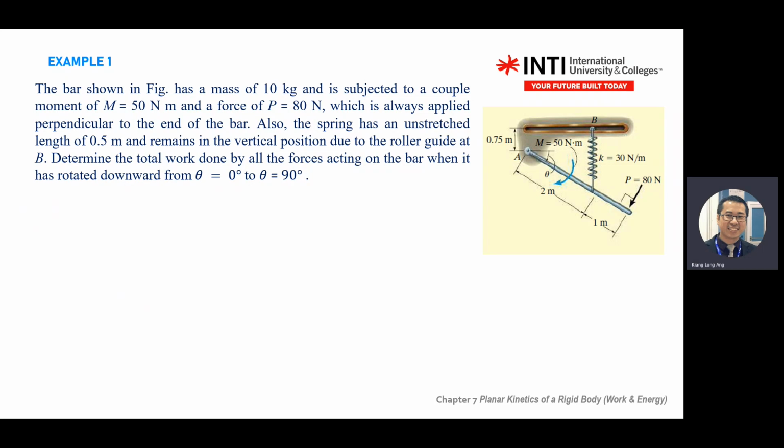Okay. Now, when you focus on the bar, although this is a rigid body, don't forget, you always need to put in the center of mass, G, in your free body diagram. Because as you learn more and more, you tend to forget already. Actually, there's a center of mass there. So remember, for a rigid body always start with the center of mass. Go and pinpoint where is the center of mass. Then draw W going down in your free body diagram before you forget.